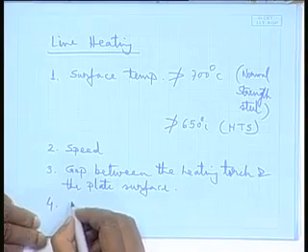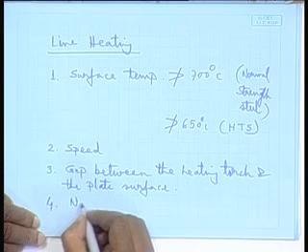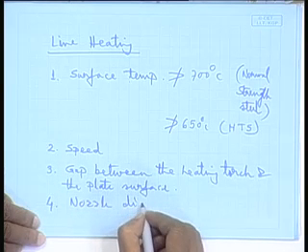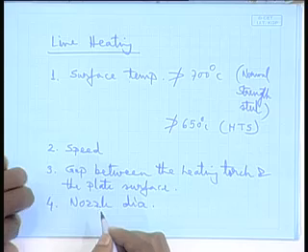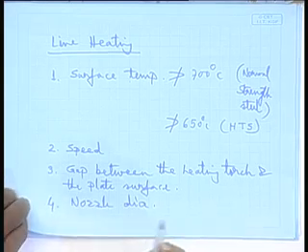One of the cheaper or easier sources could be gas flame heating. If that is used, this gap is important. Another aspect for oxyacetylene heating would be the nozzle diameter, because the nozzle diameter will determine how big a surface is being heated. Based on that, the heat distribution and heat flow, that Q by S quantity, will vary. So nozzle diameter is also another important aspect.